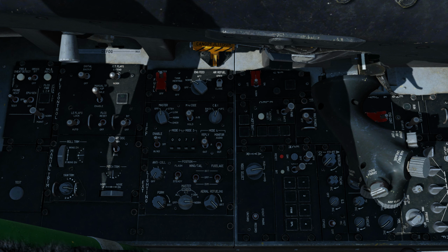Note that hydrazine is limited and is exhausted after approximately 10 minutes in normal use. It is important to land the aircraft within that time. Place EPU in the off position, then return it to normal. Check that the EPU generator and EPU PMG lights are off.